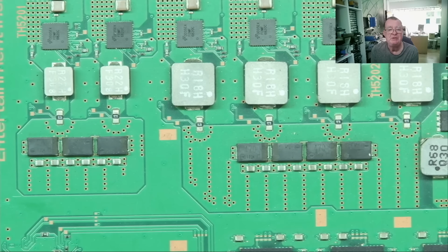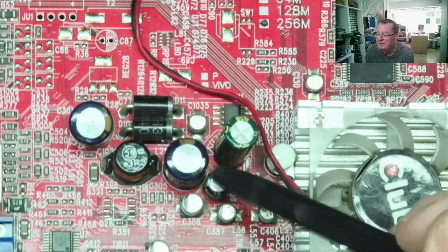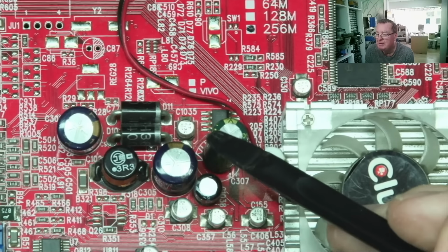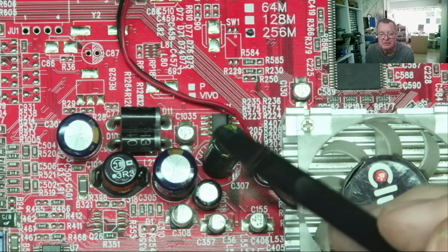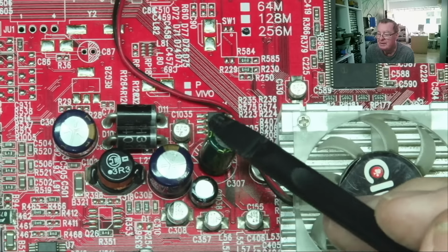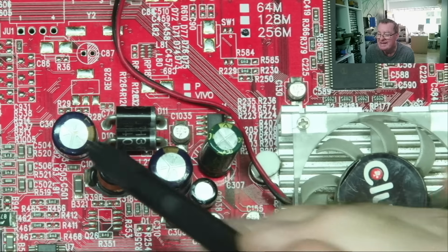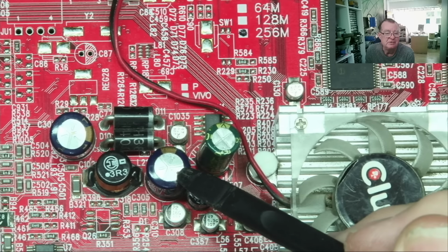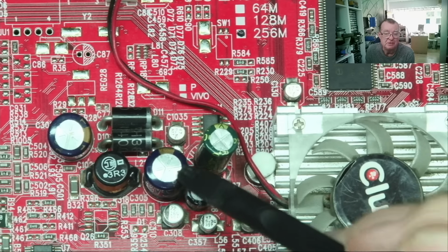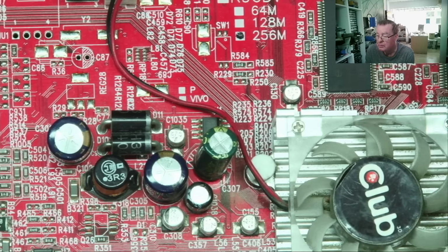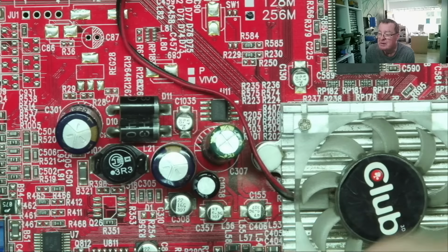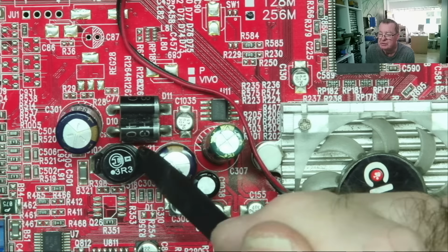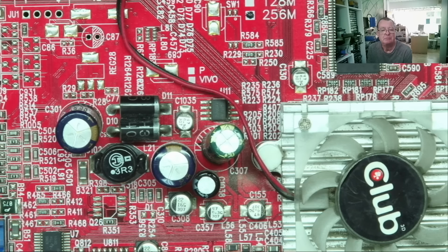So capacitors are not so unreliable really. The capacitors which fail like this and worse generally fail in such a way that the capacitance decreases, maybe to half its rated value or less, and the ESR, equivalent series resistance, which you need an ESR meter to measure, goes up. Okay, so high frequency switching circuits, those capacitors, especially from that era around the year 2000 plus or minus a couple of years, is where you're likely to find that problem.